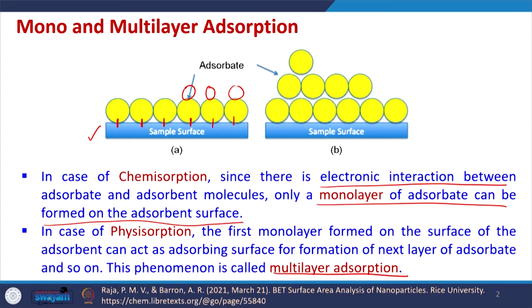If any multi-layer adsorption is occurring, there are only 2 possibilities. One possibility is that all the layers are physisorption only. In the second case, the first layer may be chemisorption and the subsequent layers, if formed, will be physisorption, but these can be determined only from experimental data. And for analyzing this multi-layer adsorption, BET is one of the common isotherms which is used for determining this.